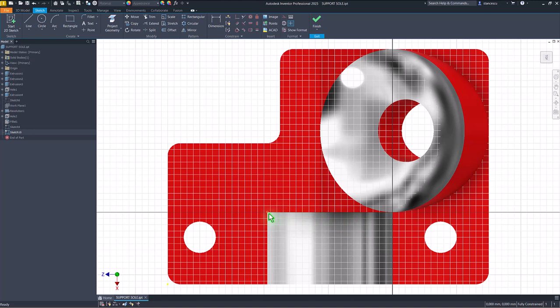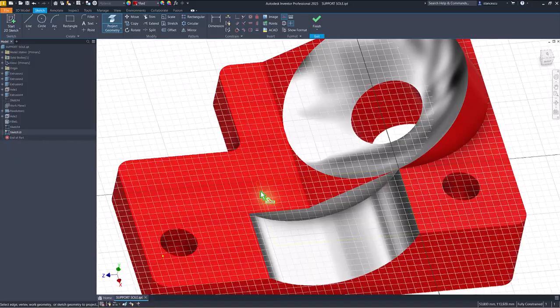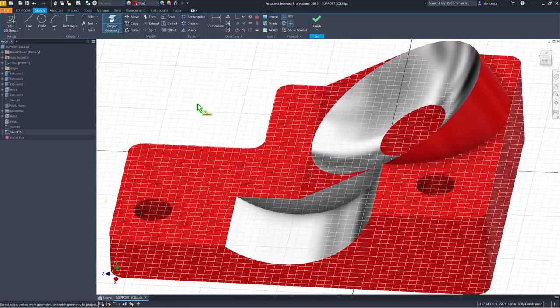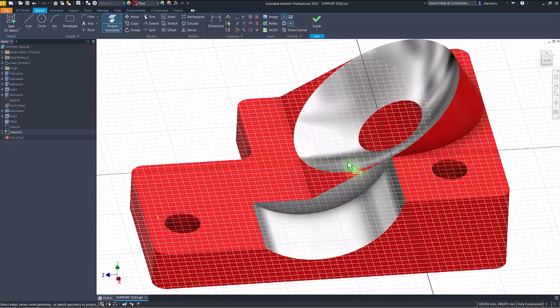If you want to project this contour and you want to obtain construction entities, then go here to this tool, construction, and apply project of this line, this line, this line, and you see also this line. You see there are here construction lines directly, not forced to be so. Why use this?